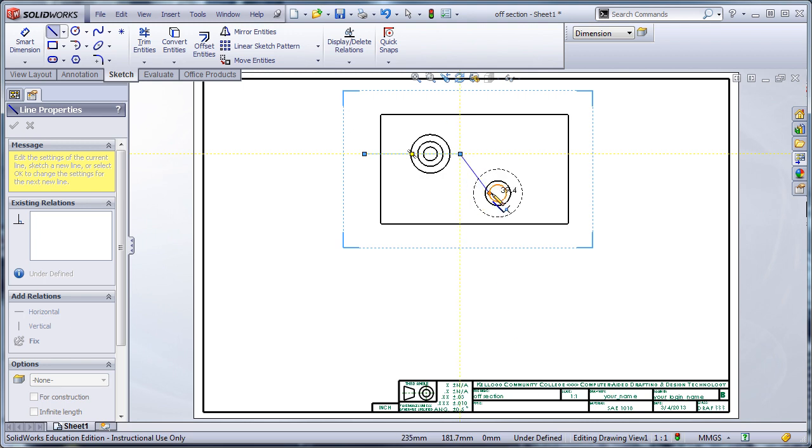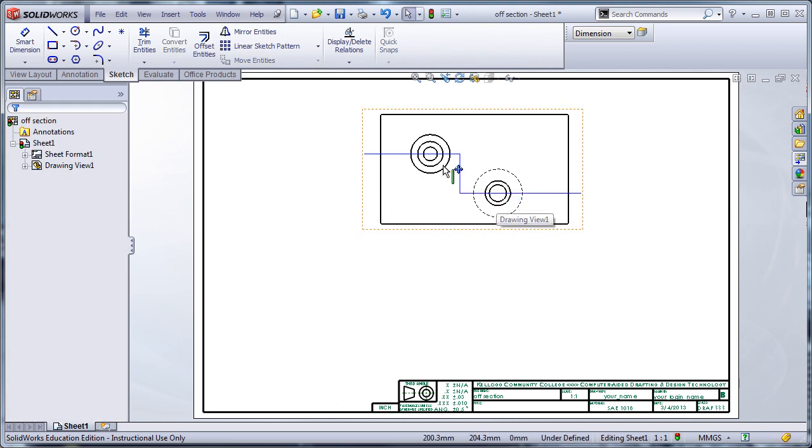And then I'm going to come down, and we'll acquire and move back to the right. You can see I have witness lines in both directions. You've got to make sure you pass dead center through these holes. If you're not getting witness lines, again, drop a couple points on those hole centers, relate them, and then delete the points.